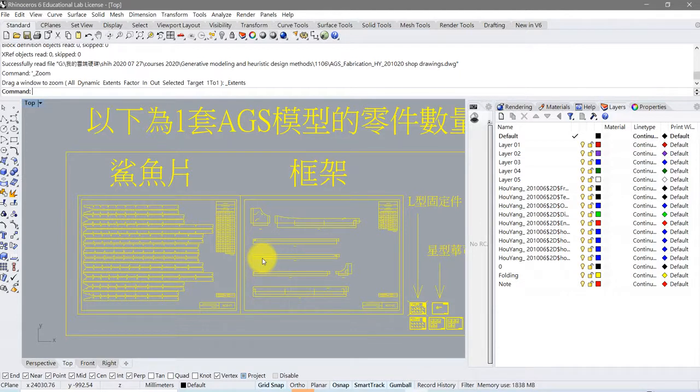And you can also ask Vector Lee. He has courses teaching robot arms. He's an expert on the laser cutting machine. I don't think it will be a problem because we also have assistants for the laser cutting machine. So I think you need to register with someone, and there will be an assistant, and you can show him the shop drawing. Then depending on what kind of material you want to use, you set up the intensity of the laser.